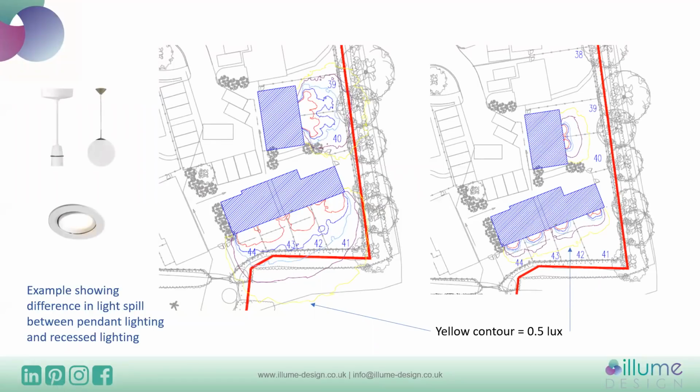An example of the difference between recessed and pendant lighting is quite useful to actually see how much of a reduction you can achieve. So the yellow line here is the light spill from a group of domestic dwellings with pendant lighting, which is this type of lighting here, suspended basically from the ceiling, compared to recessed lighting, so downlights within the properties. Again, on this side, you can see that the yellow 0.5 lux line is significantly reduced, and it can bring it down from about 30 meters spill to about 8 to 10 meters spill, depending on the scenario and the glazing involved.